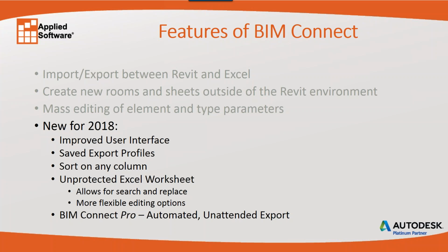If you do edit a value that shouldn't be edited, that's normally not editable, Revit will just ignore that when it's imported, and you'll get a report saying, hey, this was ignored. So you won't be doing any damage. But by having it unprotected, we can now do a search and replace on the Revit data, and we get much more flexible editing options in general, which I'll be showing you.